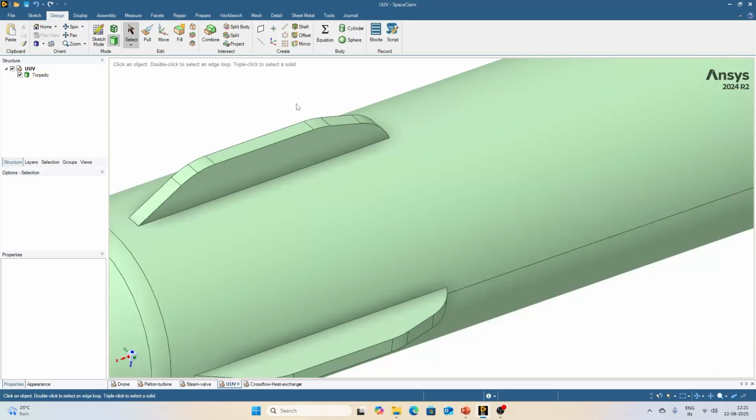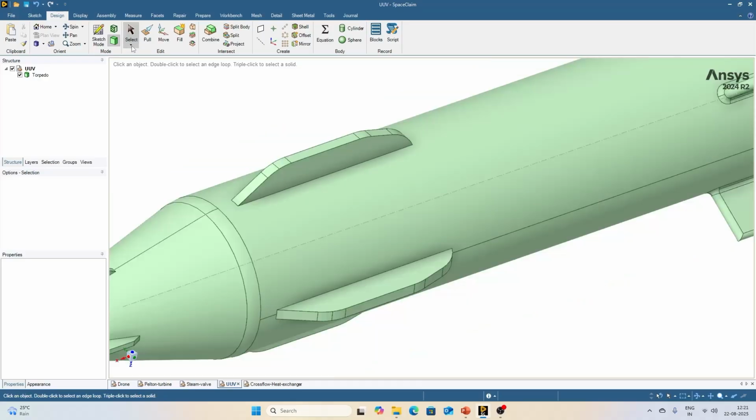The other option to select the object is using box select. This is a convenient option to select multiple geometries at once. You can find that option over here using box. Once you click this option, you will notice a small rectangle that appears by the arrow. This represents that you are inside a box selection filter. Holding down a left click and drawing a box from left to right will create a box.